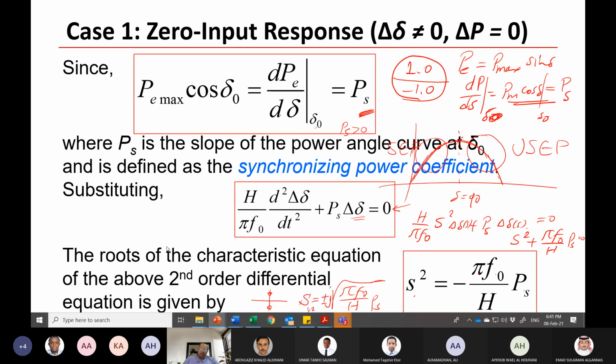And how much is the damping here? If these are the roots, how much is zeta? How much is zeta, if the root is here? 0. Yes, you are right. And as you mentioned, zeta equals cosine of this angle, and this angle now becomes 90 degrees.